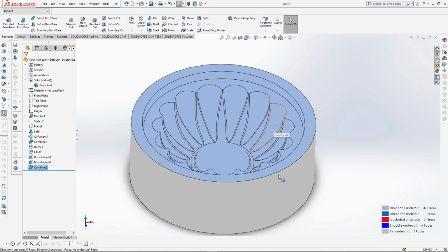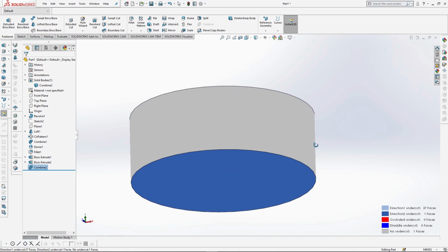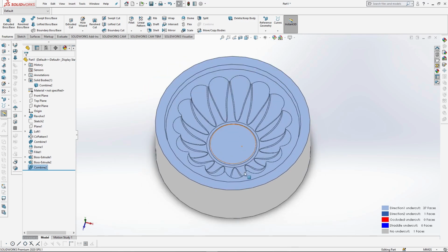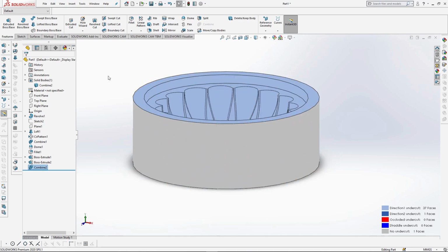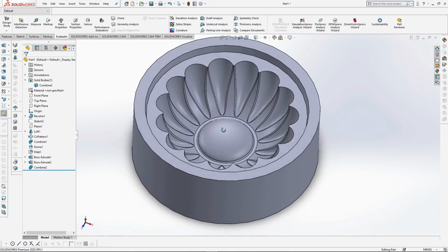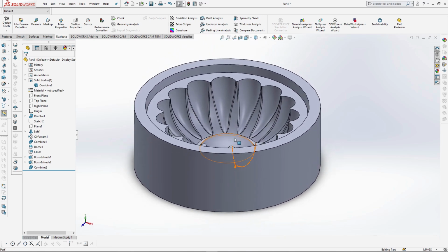When the bowl model has been subtracted, the undercut analysis has now applied to the bowl mould. Here I can see all the inner parts of the mould are light blue, as the direction for removing a cast model from this mould would be upwards. I can now turn off the undercut analysis by going back to Evaluate and clicking on Undercut Analysis. Doing this will cause the key and colour shading to disappear from the model.